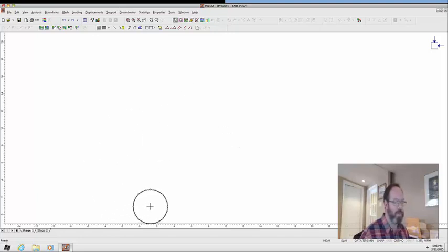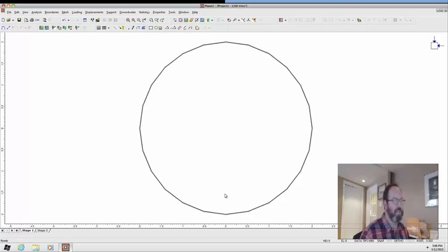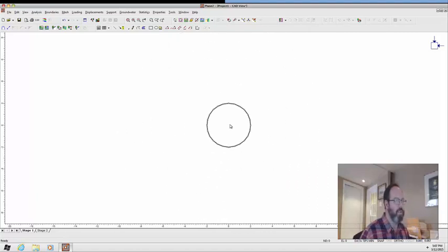So just to show you another trick, I go down to the bottom right. You can see that there's a flashing icon down there. And I'm just going to enter 0, space, 0, enter. And there's my tunnel with 24 segments with a radius of 2 meters. I'm going to go up here in the zoom controls, and I'm going to zoom all. See the tunnel. Okay. So now I'm going to zoom back.